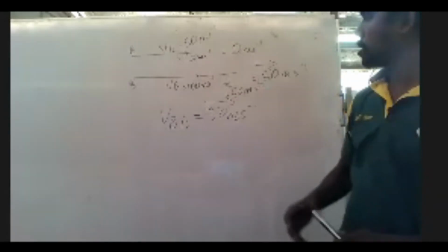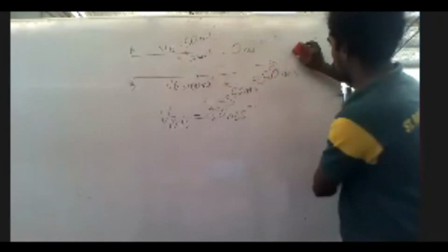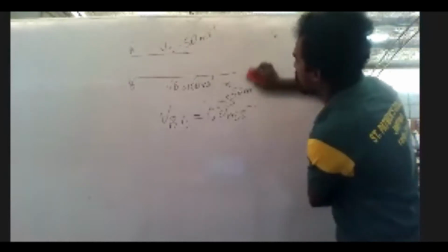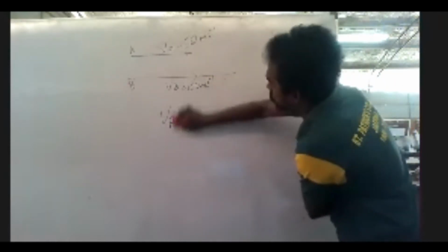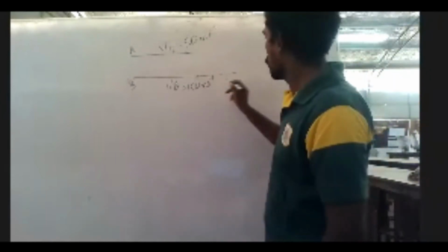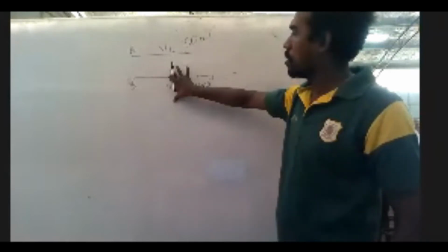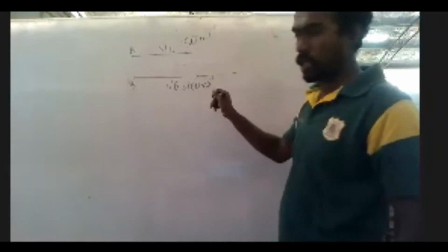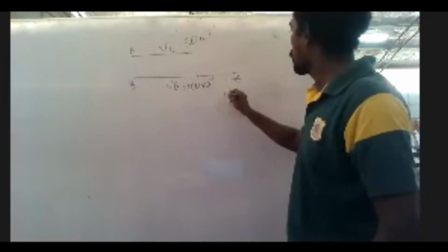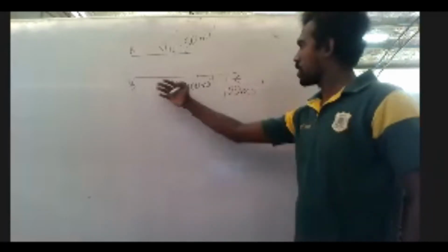Say, for example, a similar case, where the velocities and everything are the same. Now I am going to see the velocity of A relative to B. Relative to whichever body we are going to look at, we will stop that body. So I will stop B. To stop B, I will apply 100 meter per second this way, since it is already moving the other way at 100 meter per second.